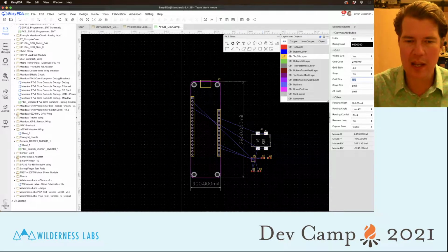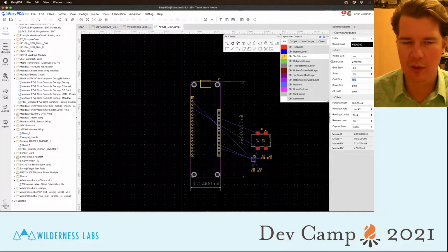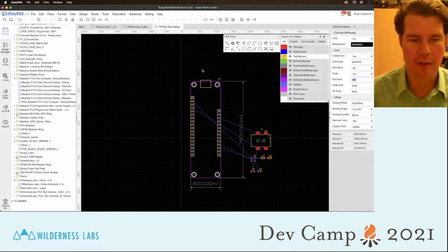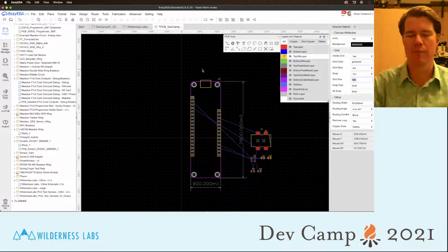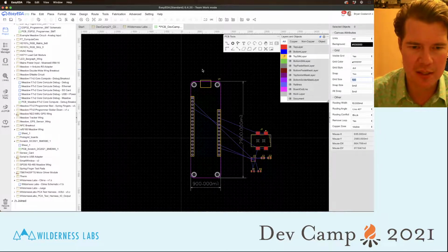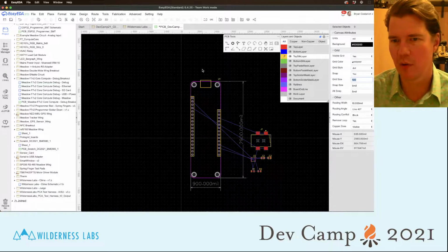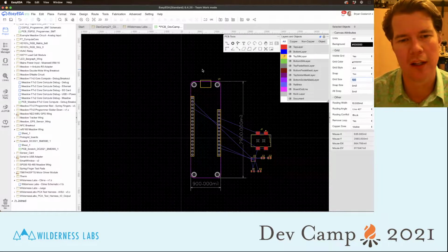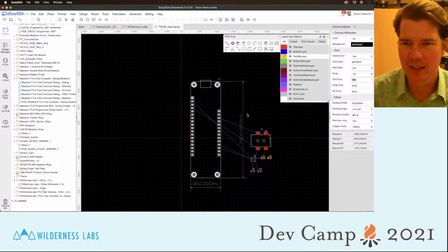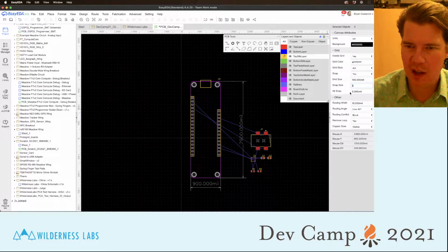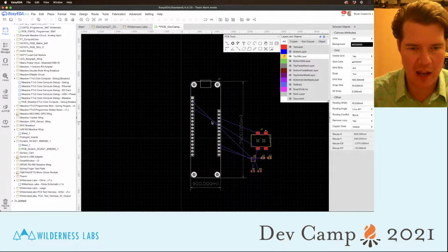So when you're laying out components, you'll often work in mils, but then when you're working on the outline of the board itself, I often switch over to millimeters because I like to design my enclosures and my products in metric. Otherwise, it's really hard. No one likes to work in imperial. It's just silly. So anyway, I want to modify this. I'm going to do grid size is 100, but my snap size I'm going to change to 10, and my alt snap is going to be 5, so that's good.